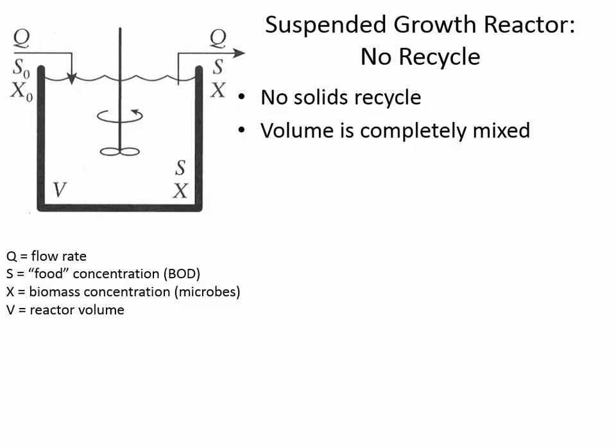Does anybody remember why we do want to have recycling of the sludge? Like, how is that beneficial? Yes? Good, right. Remember what we talked about last time was, for us to break down all of that substrate, S in this diagram stands for substrate, and that's another word for food. And the food of the bacteria is their BOD. So we want them to eat as much of the substrate as possible. By re-injecting hungry bacteria, that's going to make the reaction a lot faster.